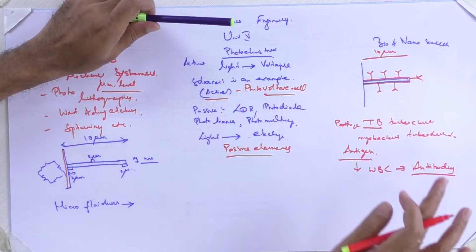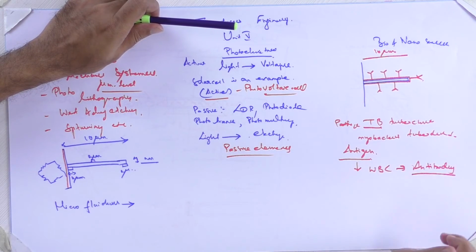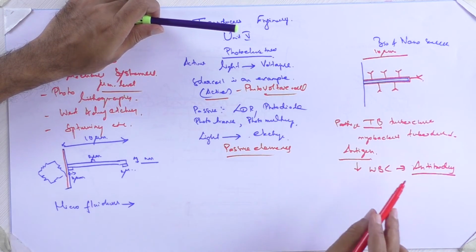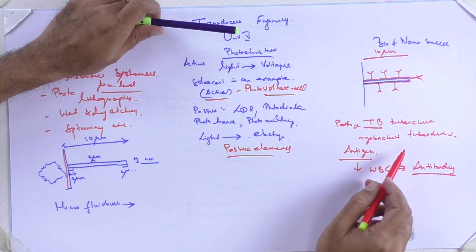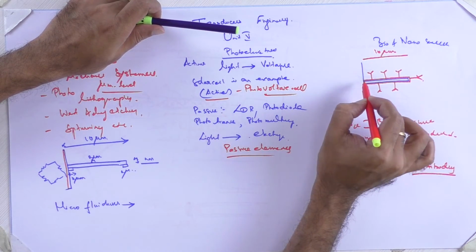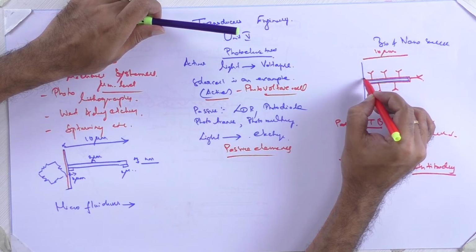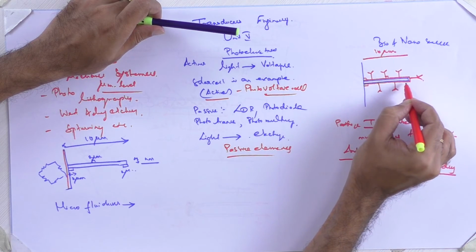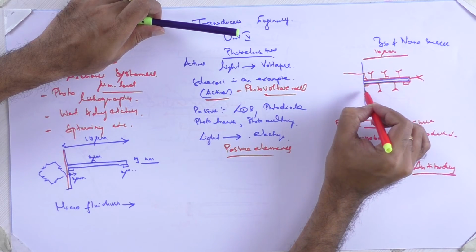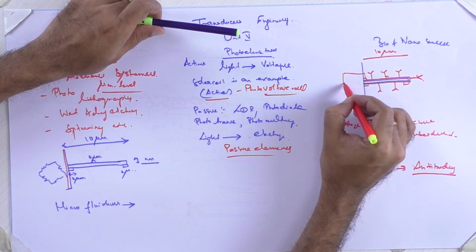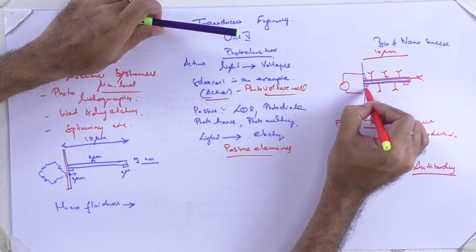Now, after coating the cantilever beam, which is of 10 micrometer thickness, with your antibody of Mycobacterium tuberculosis, we have strain gauges here and there over the cantilever beam. You can nullify these strain gauges to zero condition by normal methods.